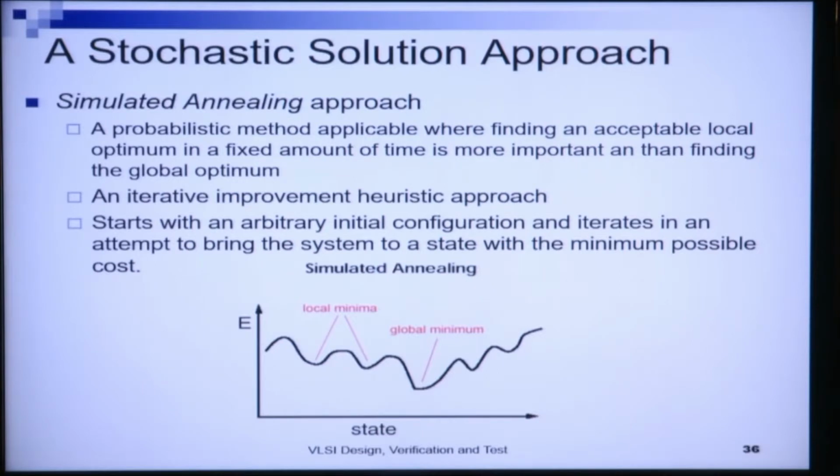And how do we obtain this minimum resource allocation? By certain allocation choices for different resources, functional units, registers, and for that we will obtain a certain number of muxes and demuxes.